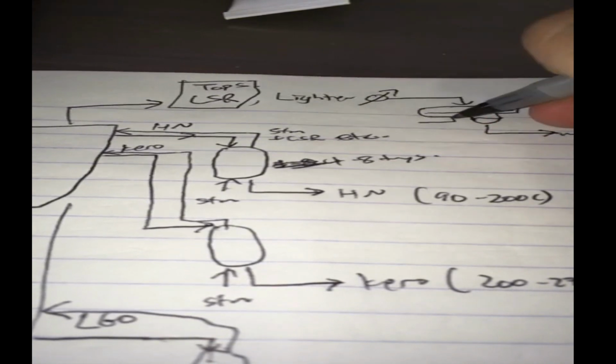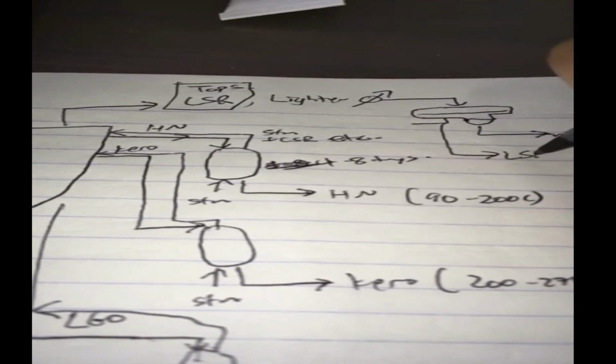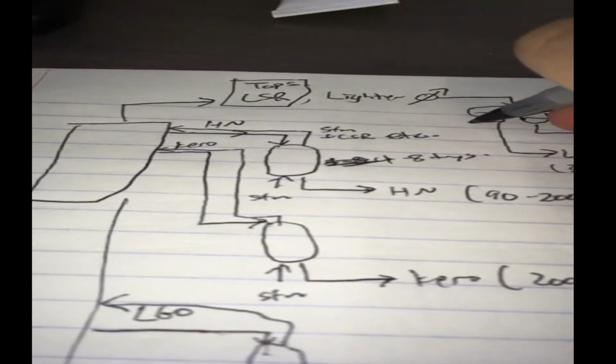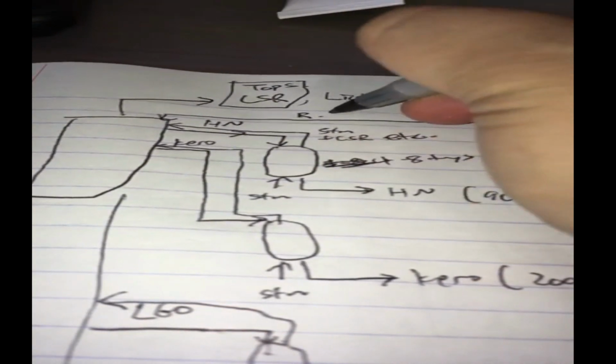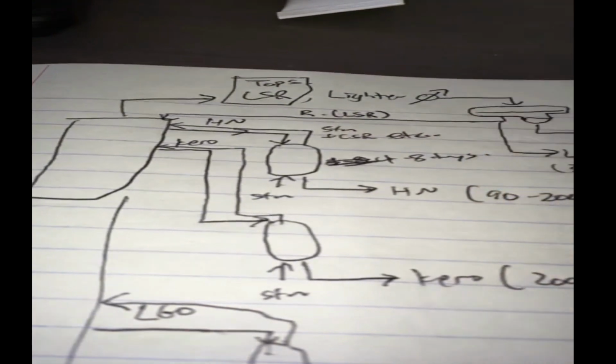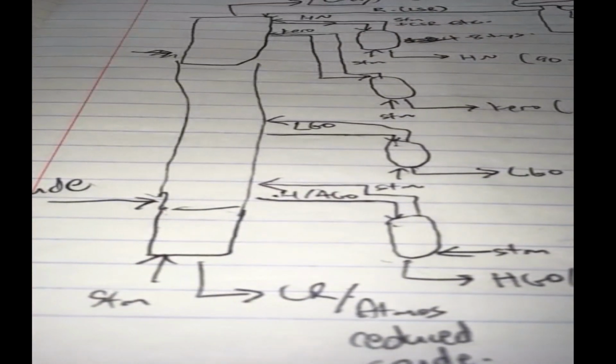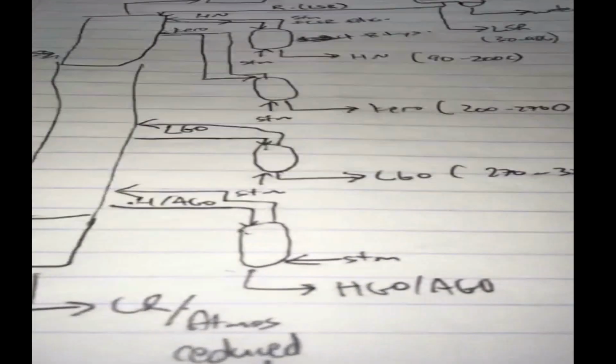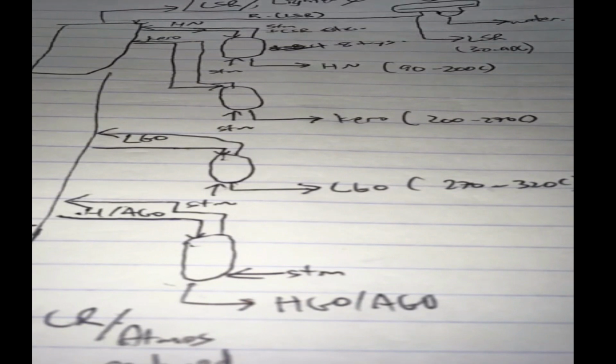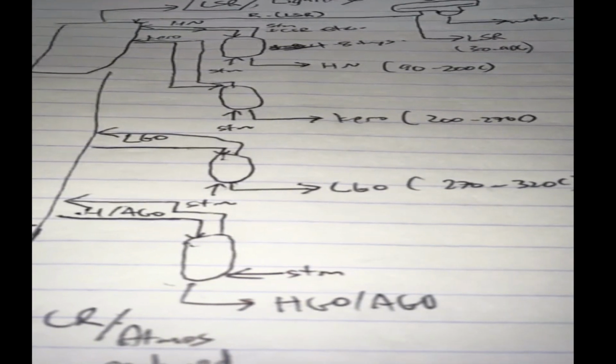And this we can draw off as light straight run, 30 to 90 Cs. This we can send back as reflux. Light straight runs or light naphtha. So, yeah, pretty good, right? That's what our crude tower will start looking like. Yeah, something that resembles a real crude tower now. Okay. Next problem. How hot do we heat the crude?